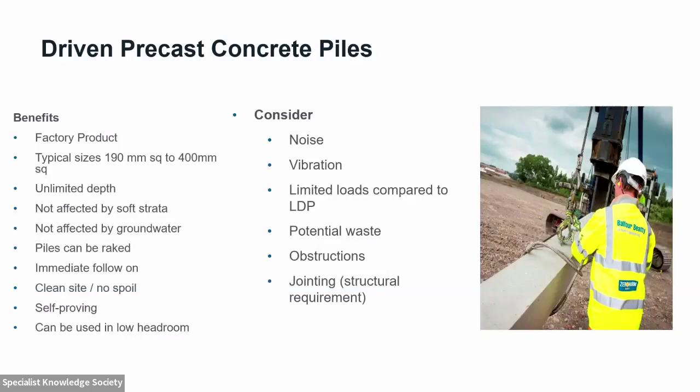So we start off with the driven precast concrete pile. These may seem as a very good solution because they tick a number of boxes. If you think about a sustainability box, these are manufactured off-site. They're a factory product. You can see them before they get to site. You can use quite efficient concrete. There is some waste, but there's minimal waste if you can drive these piles correctly to the right depth. So they're very good and a useful foundation solution.